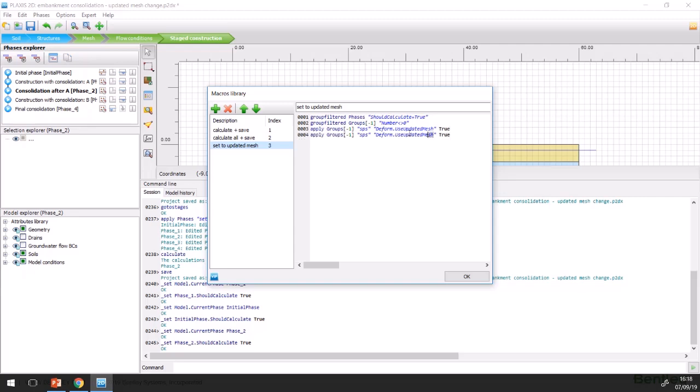Since we're using Plaxis 2D, we also want to use updated water pressures. So this is for 2D only. And what you want to do, let's copy again this one. And we might also want to change the max steps stored to be 20.